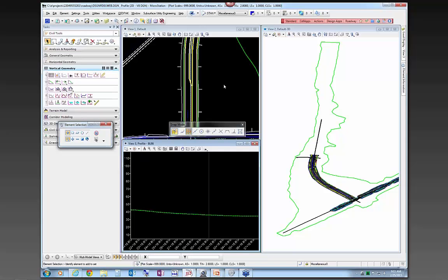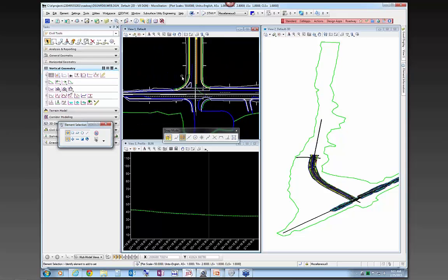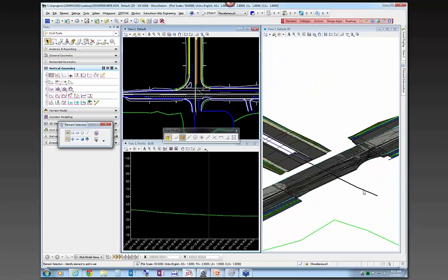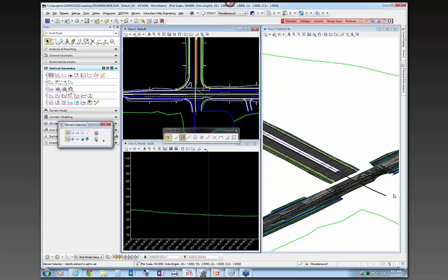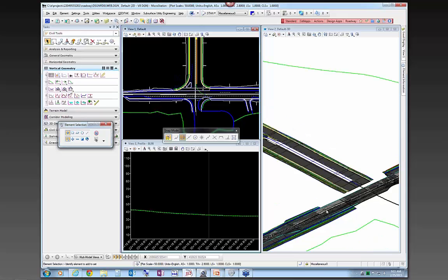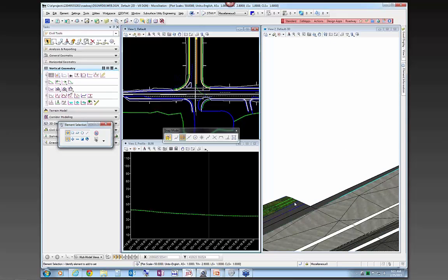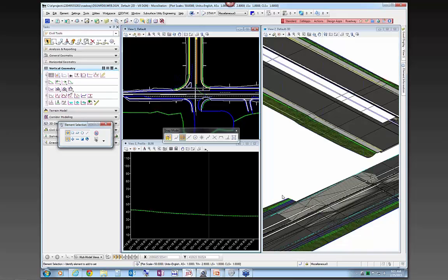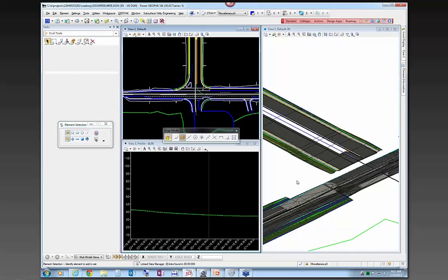And I want to talk about the three views that we have here. I'm going to keep this snap mode here, but let's talk a little bit about the planning stages. If you look at this corridor right now, as we left off in Chapter 7, and then we applied superelevation in Chapter 8, we stopped our corridor short of the intersection, okay? And now you notice that I've already planned for this, if you will, intersection gap in here. And the way I did it in this case was with switches, okay?